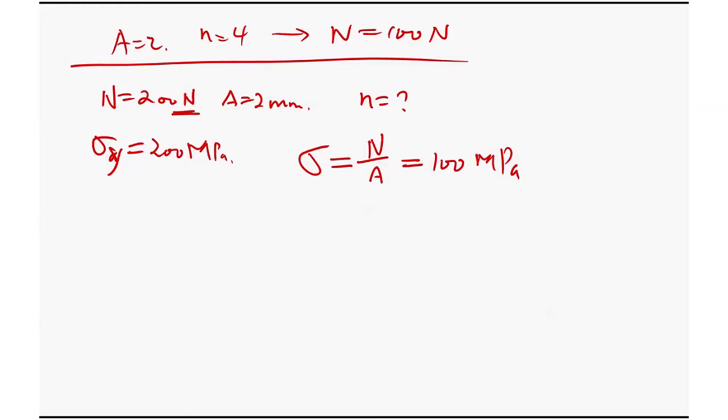So now I calculate in this cable, if I hang 200 Newton weight there, the stress will be 100 megapascal. Now, what's the safety factor I have here for this structure? The N should be sigma y over sigma. The material can go 200, and now you're at sigma, 100. So the safety factor, therefore, is equal to 2.